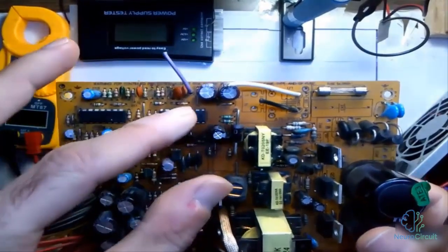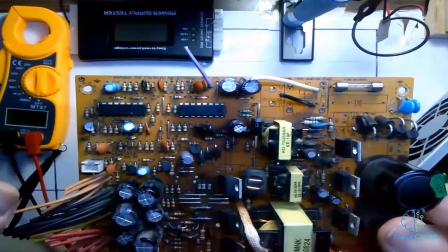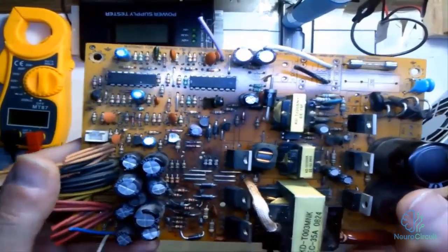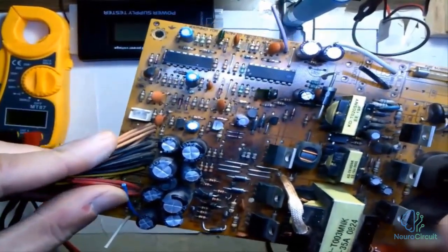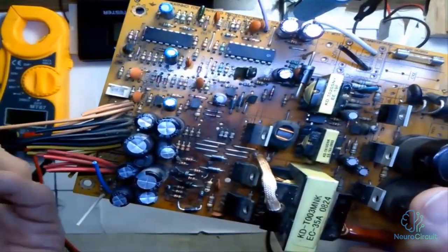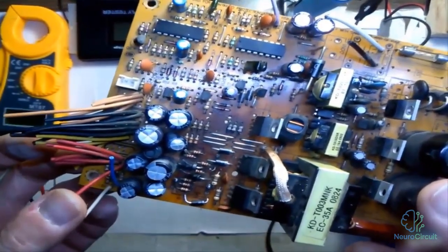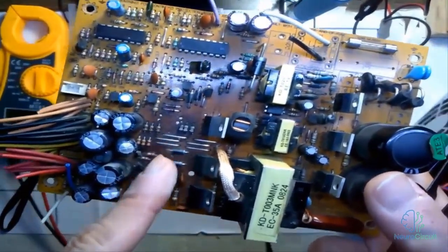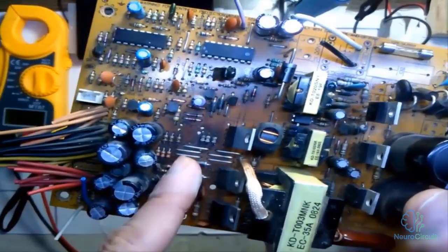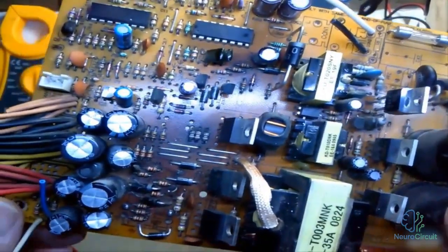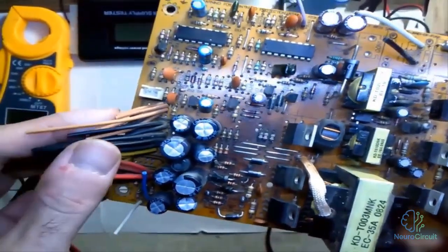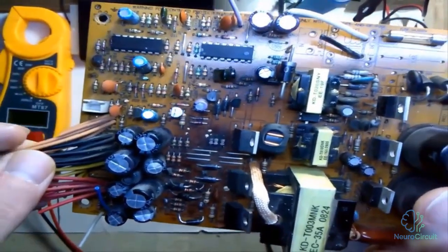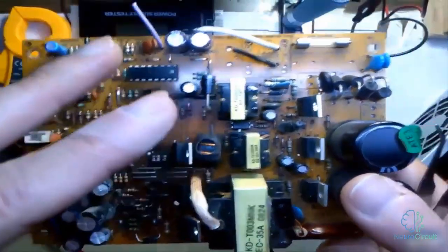If the control circuit is faulty, we need to test the control circuit, and if the overvoltage circuit is faulty, we need to test the overvoltage circuit. And if our output voltages are not correct, and we see, for example, that the 12-volt line is giving 11 volts, or maybe it's giving 13 volts instead, in this case, you need to check the components related to the output, such as Schottky diodes, MOSFETs, inductors, and so on. Test the regular diodes placed here and even the capacitors. Their job is actually to stabilize the output voltage.